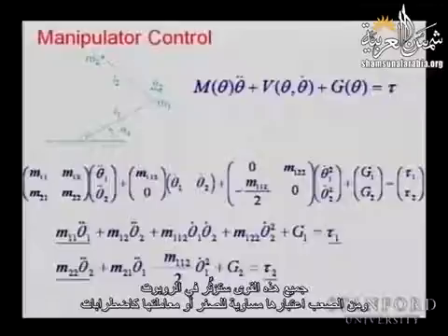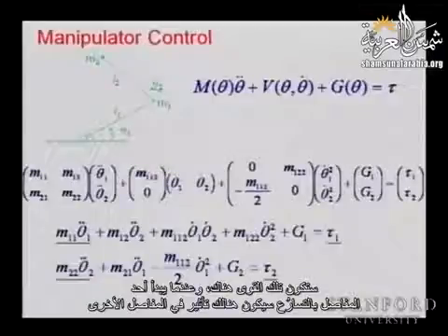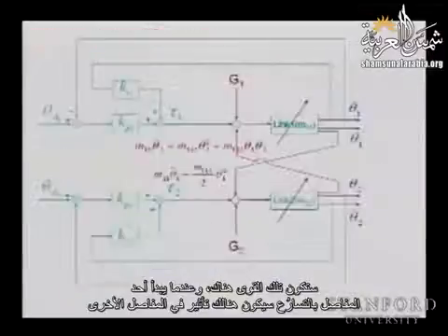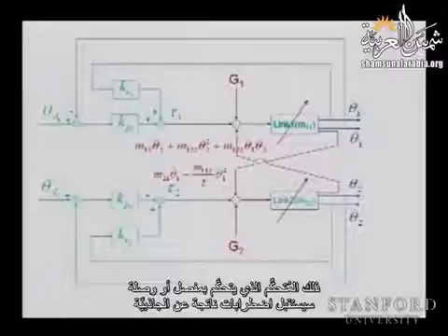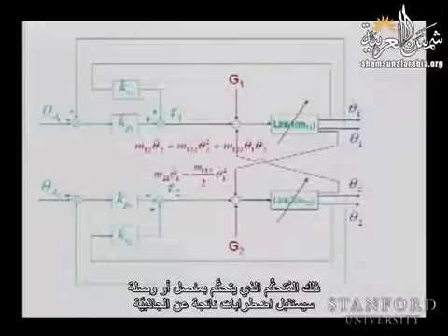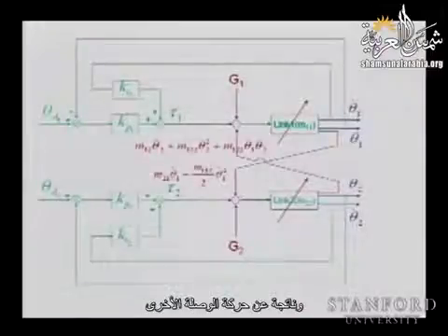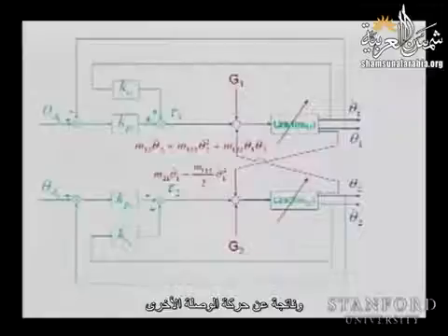All of these are going to have an impact on the robot, and it's really difficult to imagine that these are zero or to treat these as disturbances. They are going to be there, and as you accelerate one joint, you have an effect on the other joint. So the controller that is controlling a joint, a link, is going to receive disturbances coming from gravity and from the motion of the other link.